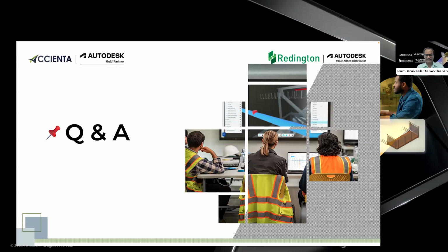We have another question saying that during exporting videos, there is a lot of flickering of light bouncing in Twinmotion. Is there any way to sort it out? I would say that there are a lot of other settings that we need to play around with, so I think that can easily be fixed. It also depends upon the type of light that you are using. The light should have the IES parameters so that it will have the proper parameters.